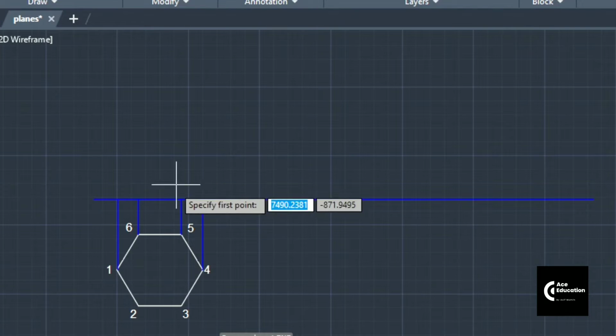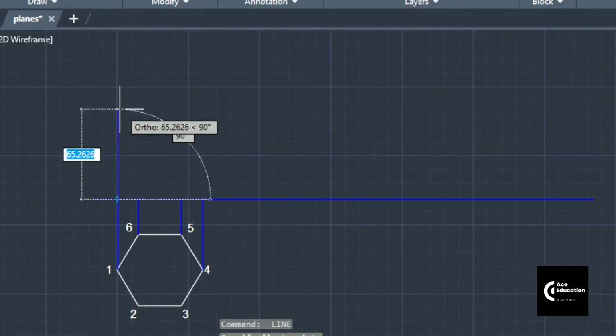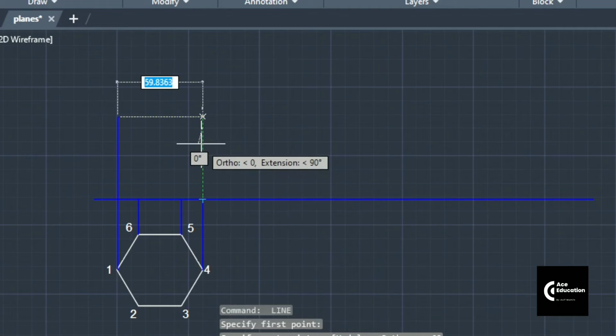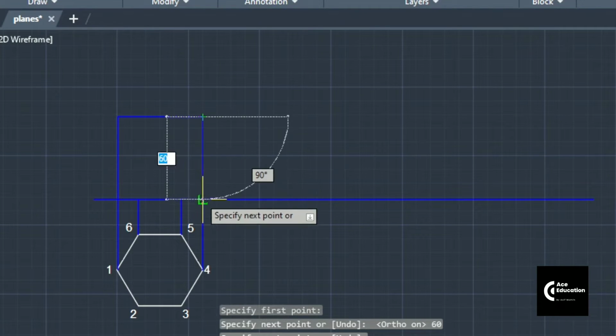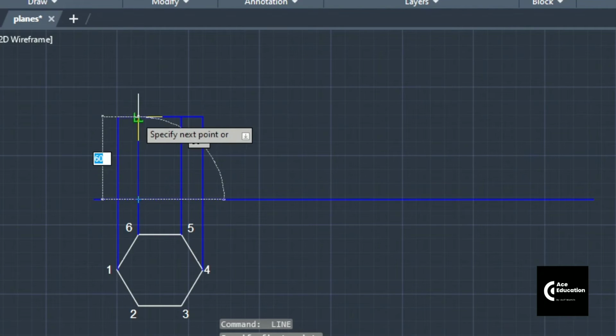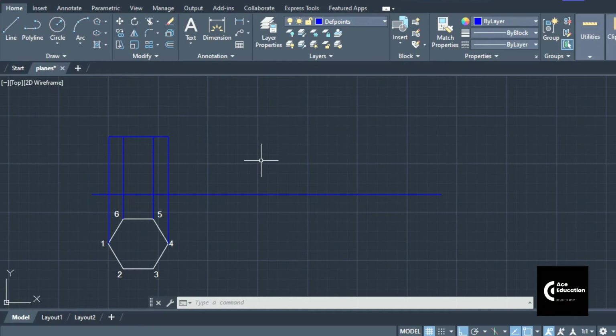And now we'll draw the rectangle of 60 mm height. So make ortho mode on, give 60, enter. I'm drawing this front view in projection layer because once you are going to cut this prism, the removing part should be in the projection lines, while the other part, the retaining part, should be drawn in the dark lines. So initially I am drawing this whole object in projection layer.